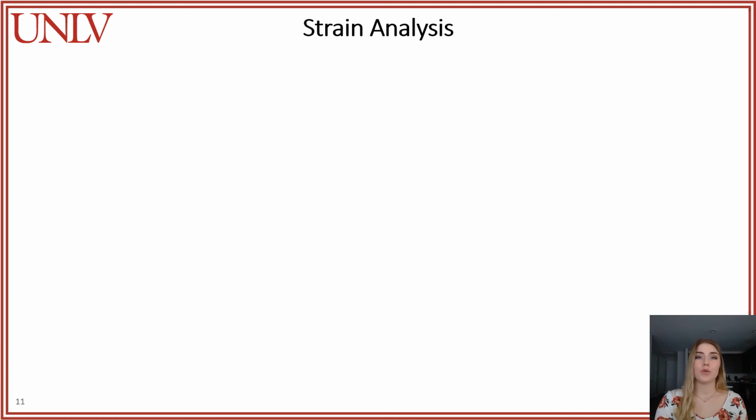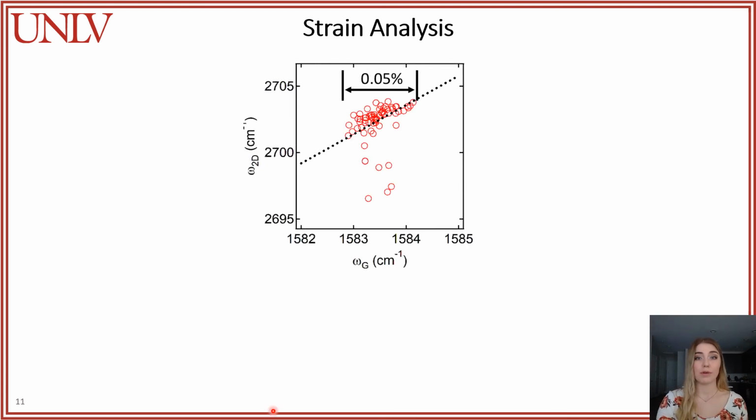We measure the total induced strain from the spread of the 2D and G frequencies. Crystal strain with random orientation is about 1%, and our analysis shows that the strain induced by the fabrication process is about 0.05%, which is extremely low.